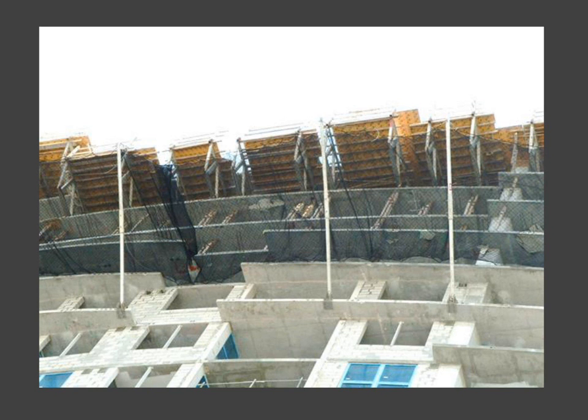So what you do is you put a safety net that's only 25 feet or less below them, and then if they fall off, they fall into the net. Tools and other materials fall into the net, and that's a good way to provide safety equipment where you can't provide the normal standard thing that you would use.